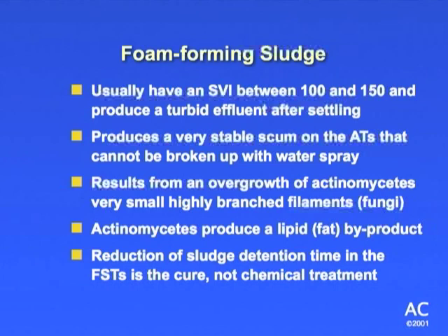And again, there's variations on this. You can send these samples in to somebody like Jenkins, and they can find out specifically what's causing the problem. We tend to want to group things by here's what it generally is, but it's not unusual that you could have a plant that's got something that's totally oddball to itself, that maybe only another plant in another state's had it, or it just depends what's coming in with your influent. Septage loads coming in can throw plants, and oftentimes with a plant, it could be very short-lived. You could have something really squirrely happening for a few days, and it just works its way through the system. Other times it'll take a foothold.